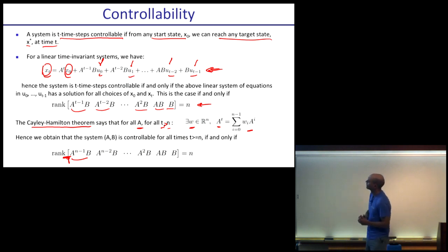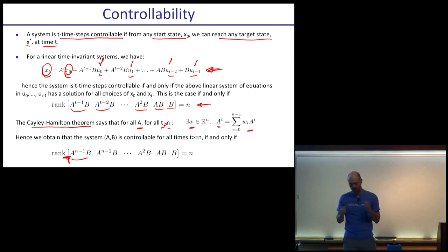And so in control theory, people often study these conditions in a lot of detail and then make assumptions. They'll say, oh, we'll look at controllable systems. And that's actually a very reasonable thing to do. We've been looking at LQR without making that very explicit. But imagine you have an LQR system that you're trying to solve, and it's not controllable. Meaning, let's say you cannot drive it to 0. Well, then the solution we've been talking about, this notion that you could drive it to 0 and then have a steady state solution and so forth, would not be true.